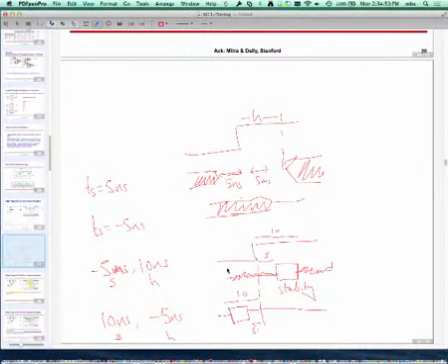What is the square in the graph? The square? Yeah, this is the region where the data has to be stable. The data has to be stable. Okay. So it can change before, it can change after, it cannot change during it. So it doesn't necessarily mean at that rising edge, it's taking the stability. It's still taking the data from that rising edge. Correct.